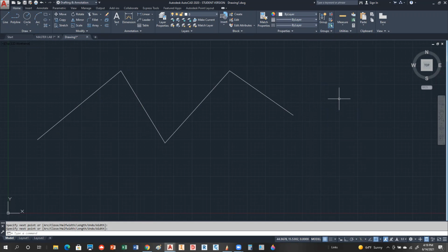We also notice that they don't look any different from lines, but if you click on this guy, you'll see that it is all one object. And of course, this guy's popping up telling me what it is. But notice those blue grips here, these are vertexes. So that's a vertex, vertex, vertex, vertex. And because I drew it from this point to this point, this would be the starting, that would be the ending, okay? So that's a big difference than just lines.